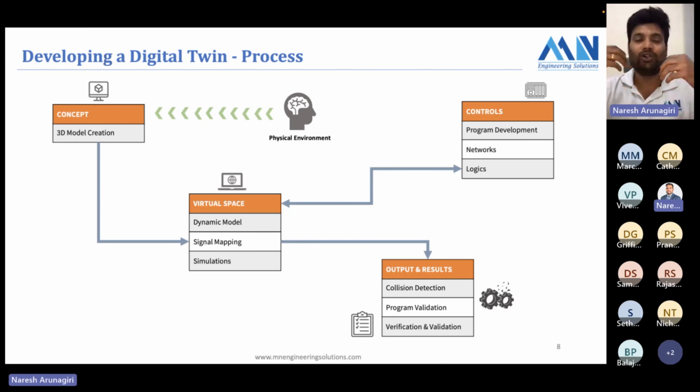How do we call a digital twin a virtual copy of your system or your machine in a virtual world? So when we talked about it, Burr Oak Tool gave us the 3D model of the machine. But the 3D model is just a dead body. It doesn't have physics to it, doesn't have motor skills, doesn't have any dynamics to it. So in order to do that, we need to import the model as parts and then reassemble it and start giving the physics attributes to it.